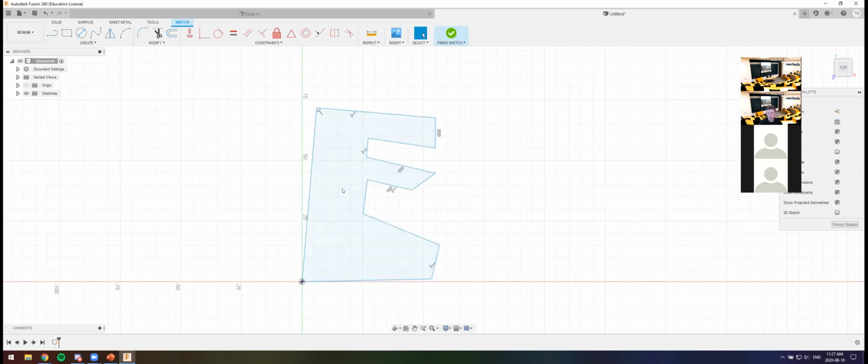Also, guys, one thing to note, when you create this E in the first place, you may get some weird constraints that happen right away that you don't actually want. So you can delete some of these. I'm just going to delete all of the constraints that it gives me. There you go. All right, letter E. Let me know if you guys have any trouble with this. But go ahead and create a letter E, and let's just start constraining. I'm going to do a couple examples, and then I'll give you some freedom to try to figure out how to do these yourselves.